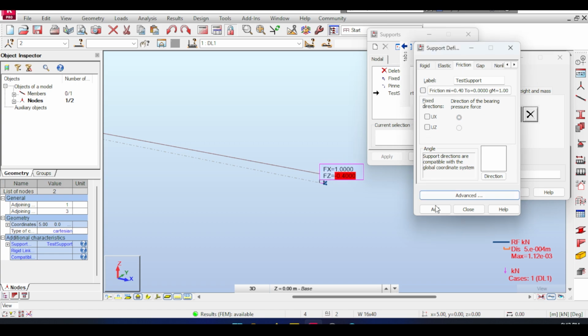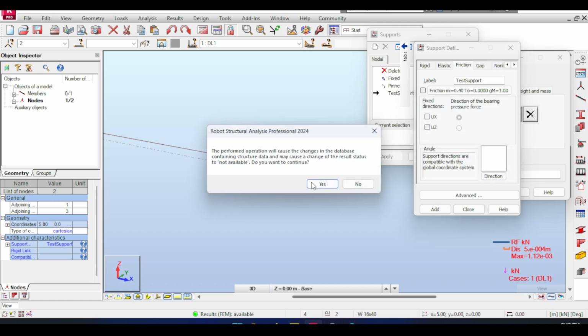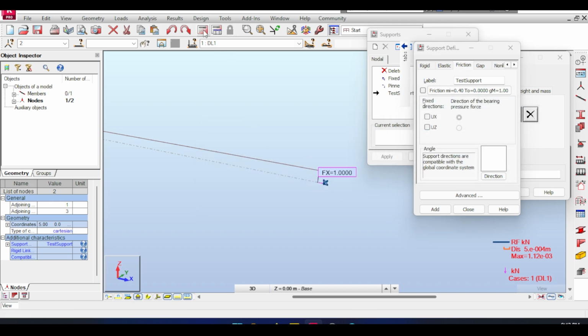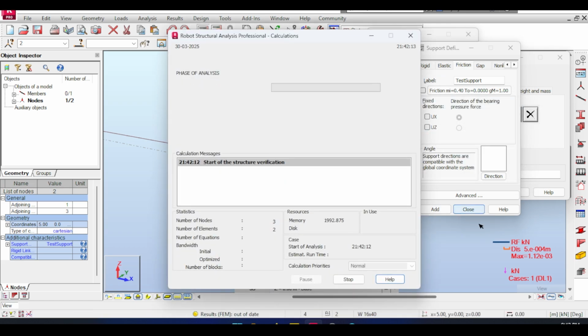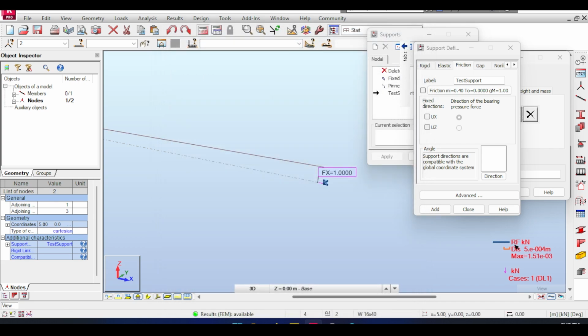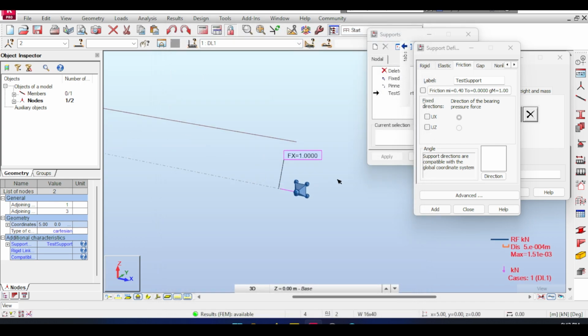I'll remove the friction here and I'll add this again. So now I'm basically eliminating everything. If I run the analysis again, I should get my trusty 1.51 millimeters, which is exactly what I get because I just eliminated the friction. And of course, this force is a relic of the past. I should delete that thing. So I'll go to loads, load table, and delete this cute force.